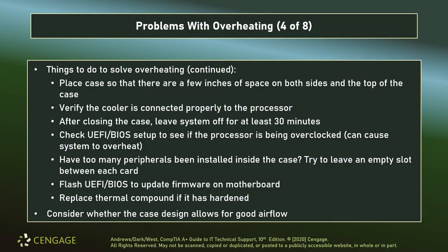Make sure the cooler is correctly secured to the processor. If the system is failing due to overheating, let's go ahead and unplug the system and leave it off for about 30 minutes. What I will usually do in that case is go ahead and take off the side panels, take out my compressed air or my anti-static vacuum, make sure everything is nice and clean, check my cable management, and just let it sit and air out for half an hour. You know, unplugged, completely unplugged.